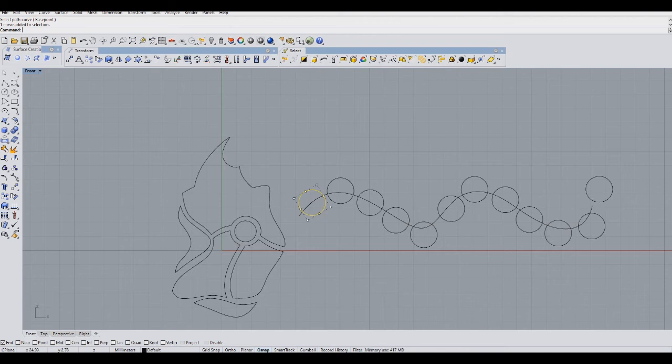And because 12 of them was a little bit more than it could fit in on the curve, you have one floating out here by itself. But this particular command can be useful as long as the path curve doesn't get really wonky. Sometimes when I've done it, I've tried to put stuff in place, but because I'm copying things that are irregularly shaped, it confuses the software and it doesn't really put things into place in a fashion that I like.